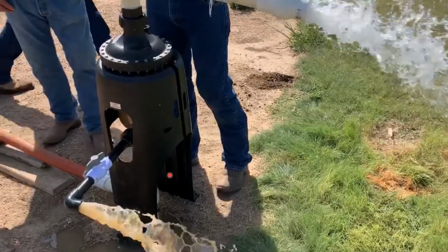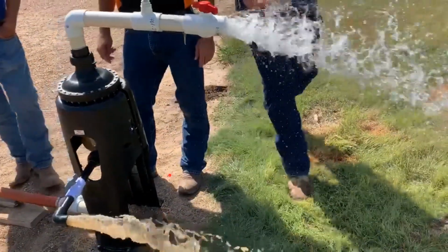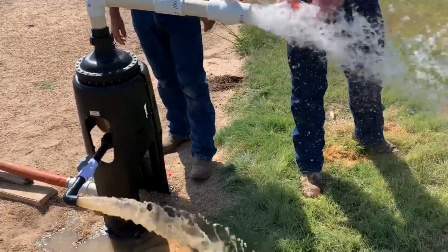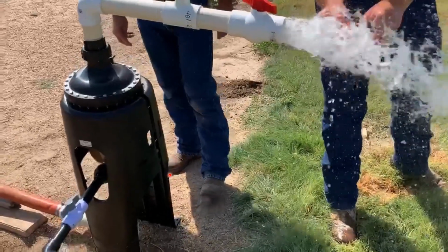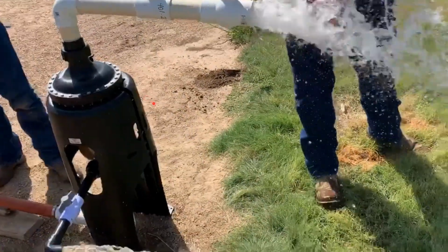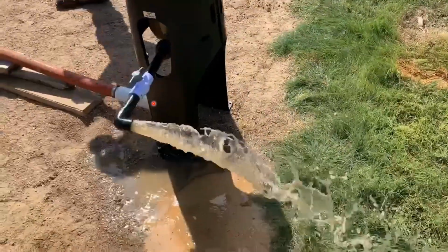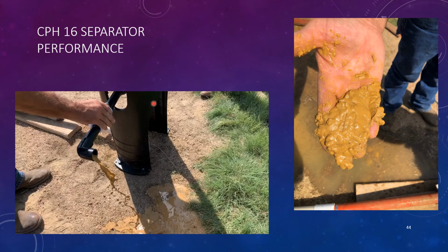This was done about 18 months ago in the field. Now this particular grower had an 80 mesh filter that was having 1 or 2 flush requirements a day. It was a manual system. And when he put this on, he was going over 30 days between flushes. And he was dragging drip tube behind his pivot, and that no longer needed daily flushings or weekly flushings or bi-weekly flushings as the situation dictated. So that then all of a sudden they weren't having to go down and take 1,000 lines and clean those out either.